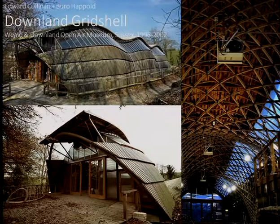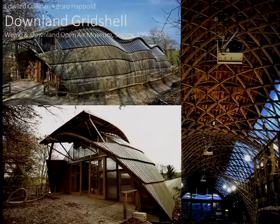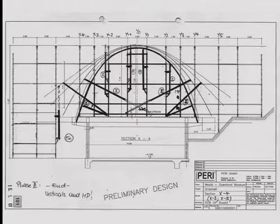The Downland Museum is another example of a timber grid shell. Again, you see there are quads because these elements must be able to rotate, move, and bend. But the way it was done was not, let's say, the system which is called push-up. This is called pull-down. So you see there is a scaffold over here. On the top of it, there was the flat grid, which was kept in position and then pulled down using these props. So that was the way they did that. So there are two ways: to push it up and pull it down.